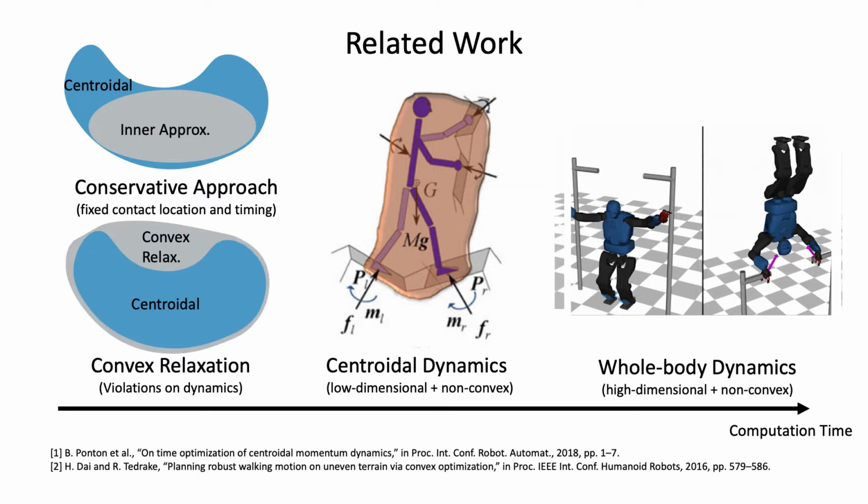Another approach is to rely on convex relaxations. However, this approach may generate unrealistic motions with significant violations on angular dynamics, unless customized solvers are implemented to iteratively tighten the model mismatch. In summary, the existing approaches commonly employ a single dynamics model over the entire look-ahead horizon, and trade off between model accuracy and computation efficiency.